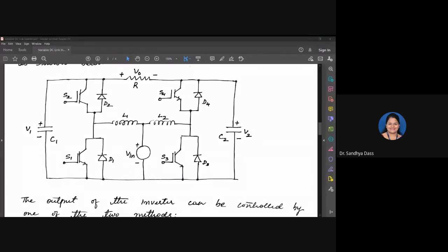Okay, you are not getting the point. In voltage source inverters, in the voltage control method, if we want to vary the AC output voltage from the inverter, what we used to do is vary the width of the pulses that were triggering your semiconductor devices or the switches, right? By varying the width, we were able to control the output voltage. So in this variable DC link inverter method, what are we doing?